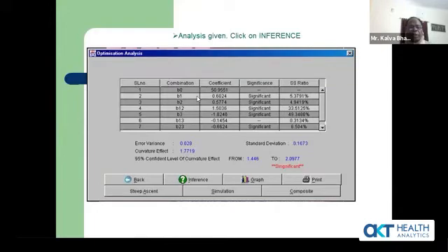It is nothing but the contribution to the process by each variable and their interactions. Now you can see x1 and x2 both have got a positive contribution, just around 5%. But their interaction, x1 x2, has got a coefficient 3 times this, and contribution is 33.5%. This is a very healthy sign, okay, to improve the process.